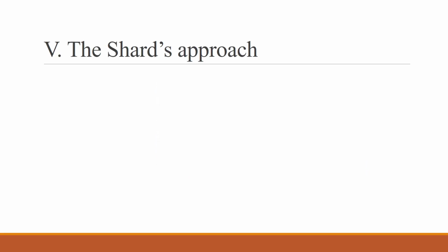This is the Shard's approach to the wind load problem, and we are going to talk about the tapering method. The Shard's building form is essentially a slender pyramid, but rather than having four similar faces, the external envelope comprises 18 separate shards. The Shard is a narrow pyramid 309.6 meters high, with sides sloping at 6 degrees.